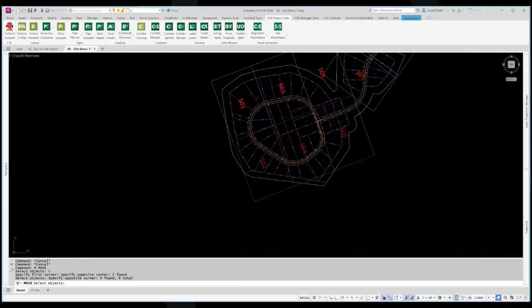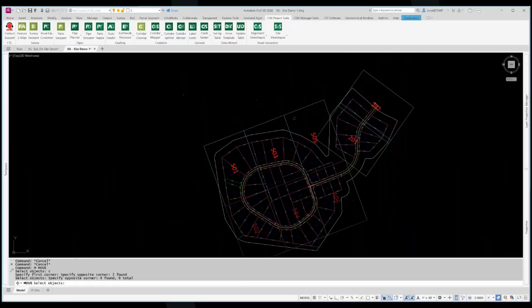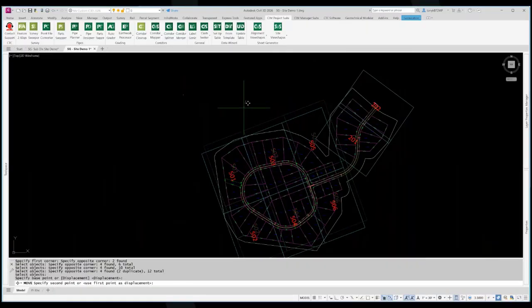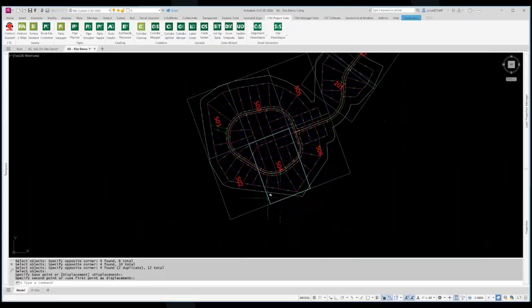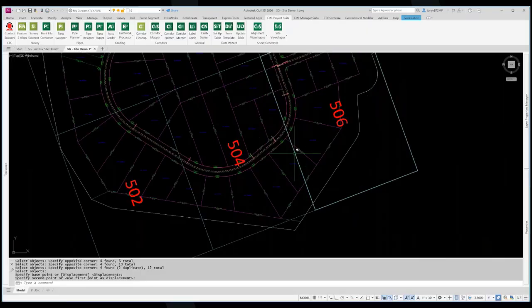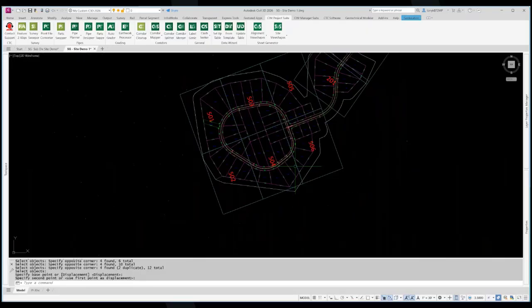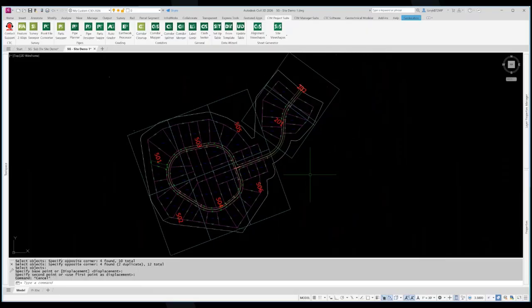And they don't have to be right in line like this. I can stagger them if I need to. It's all in just how they are laid out here. So if I want to make sure that road fits onto there, I can scooch these around however I want. But if I'm going to use a match line, it's going to want to find that match line. So just that quickly, we created those.